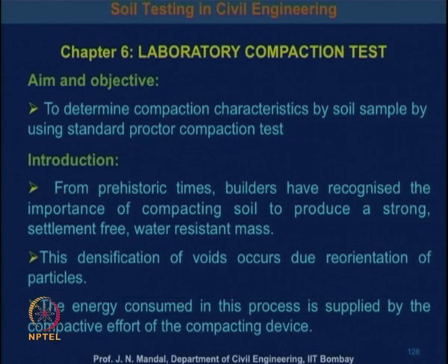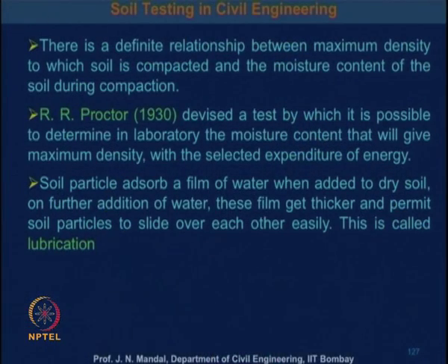The energy consumed in this process is supplied by the compactive effort of the compaction devices. So, you need to reduce the void ratio and increase the density of the soil to achieve proper compaction. There is a definite relationship between the maximum density to which the soil is compacted and the moisture content of the soil during the compaction.